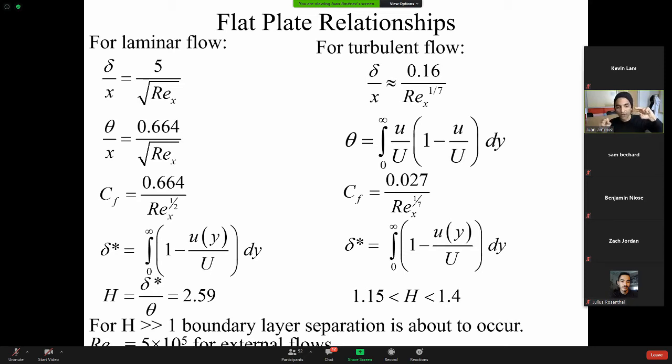Then the second term we talked about was the displacement thickness. I have the boundary layer and it has some sort of shape. Remember, we did the integral of the conservation of mass, and we said what's coming in is uniform flow, what's going out has a velocity profile. What if we make what's going out, the flux of mass, also uniform? If we do that, we have to make a gap, a distance, where no flow is going through. And that gap was your displacement thickness, this delta star here.